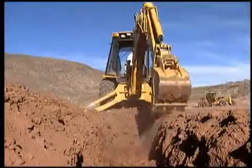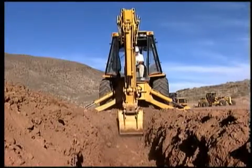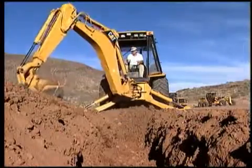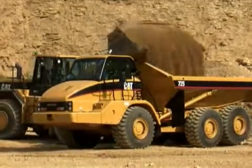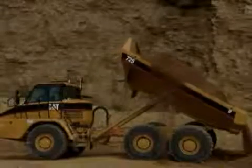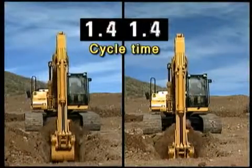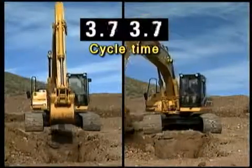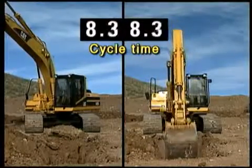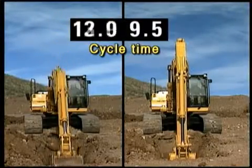Even before a breakdown, contaminants in fluid can reduce system efficiency. That is as true with fuel and engine oil as it is with hydraulic oil. A less efficient system is a less productive system. These productivity losses can go undetected because the efficiency loss is slow. In hydraulic systems, for example, efficiency can drop as much as 20% before the operator detects a change in operation. That's losing a day of productivity each week.